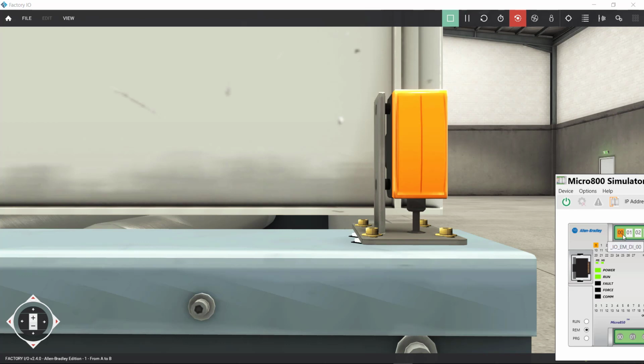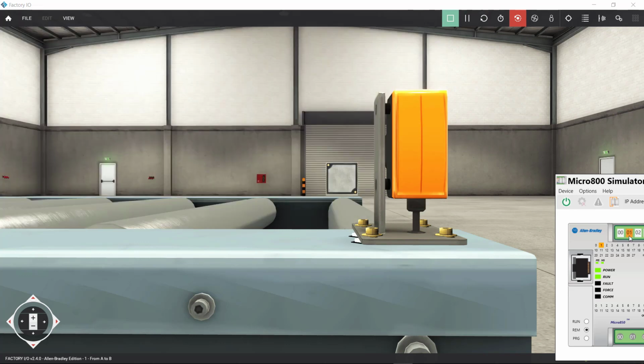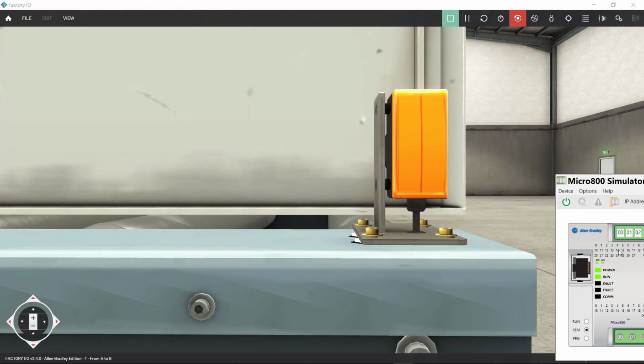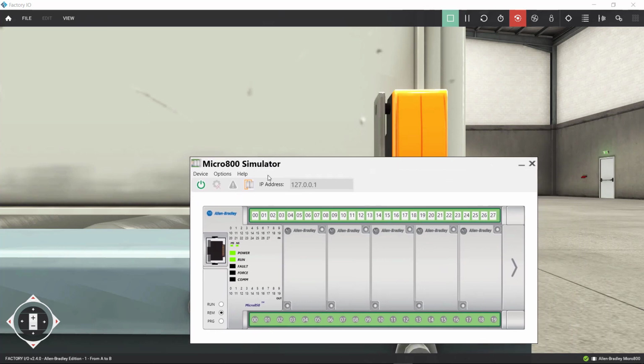So just one last time, and then we're done. All right, let me reset the scene, start it again. Now, the reason, hold on one second. Let's just wait until it stops. Bingo, you see? It never stops in the same place. And this, it's okay. It is not a problem with factory I/O. It is not a problem with the Micro 800 simulator. It's just the lag in communication between the drivers, okay?